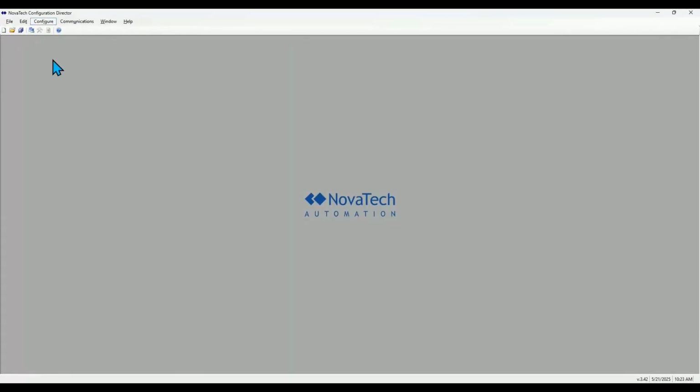So to start configuring this, and just to set the stage with you, I'm going to do a configuration on the Orion SX, but I believe essentially all of our Orion models can support OPC UA. I happen to be configuring it on an Orion SX. For a little bit of background, I do have some of the server aspects of OPC UA configured on my demo Orion IO. I'll show you the basics of configuring both of them, and then I'll be able to show it to you live. So I'm going to go configure a network port.